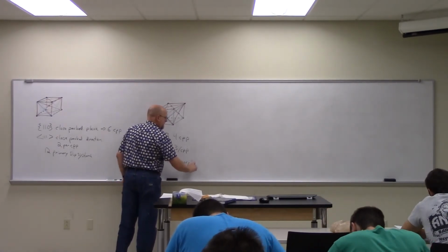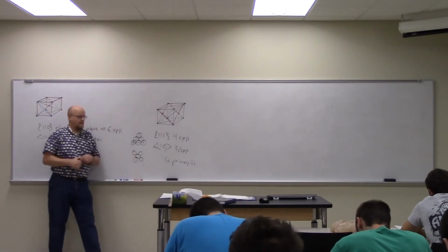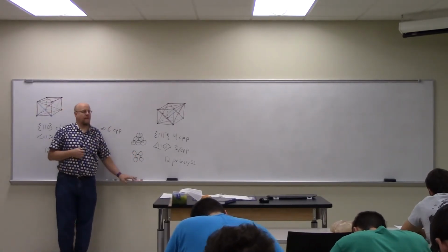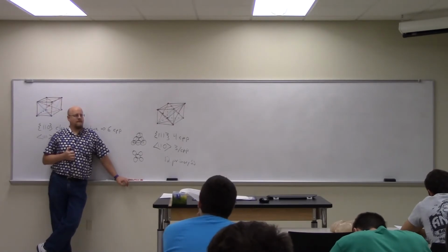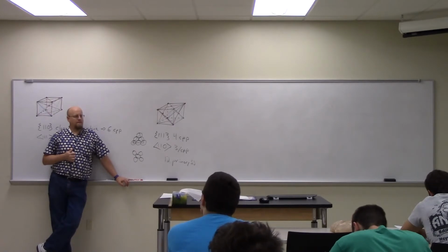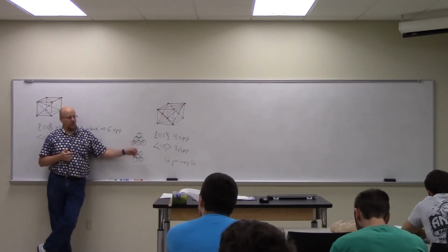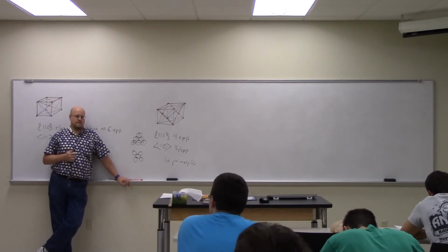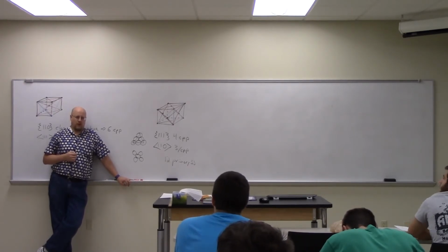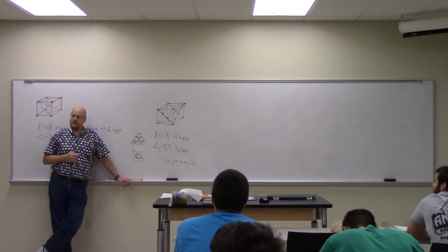Oh right, because each edge of those planes is a face diagonal. Of those triangles, you mean the triangle planes? Yeah. Is every single crystal structure going to have 12 primary slip systems? It is not. We'll go on to another example after this.